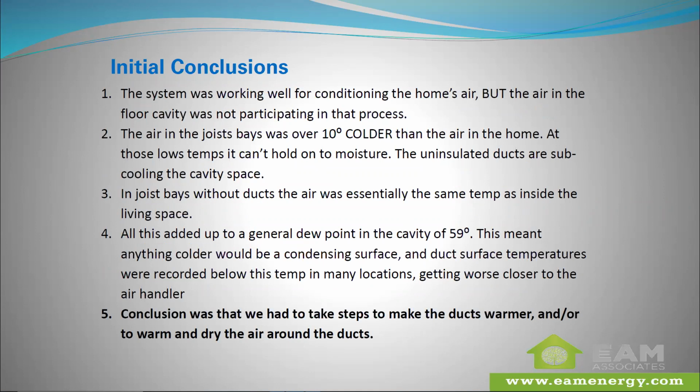So the ducts were both the problem and where the problem was manifesting itself. They were subcooling the cavity space by conductive cooling, and at the same time becoming the condensing surface. These were solid joists, not open web trusses, which was part of the problem. So the joist bays where the ducts were located were very confined.